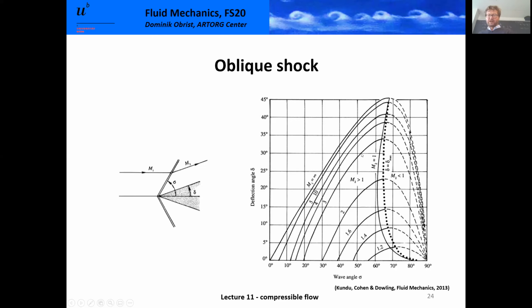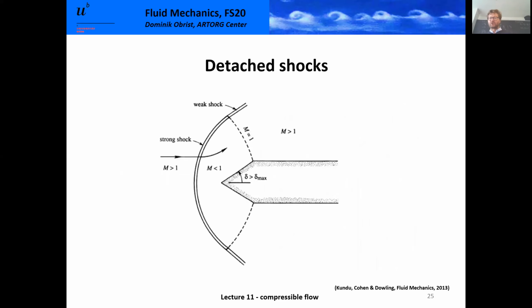There's actually, as the Mach number decreases from 3, that's this line, to 2, a critical Mach number where you have only one unique shock, and that's exactly here at this dotted line, which is about 64 degrees. So the shock angle goes from about 72 to about 64. And if you further decelerate, there is no oblique shock anymore, and we obtain a so-called detached shock. That is a phenomenon you have if you have very large deflection angles or too low velocities.